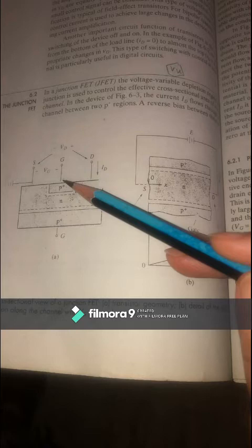And it is very clear that the voltage from the drain end of the channel D to the source electrode must be greater than the voltage from a point near the source end S. For low values of current, we can assume a linear variation of voltage Vx in the channel, varying from Vd at the drain end to 0 at the source end.